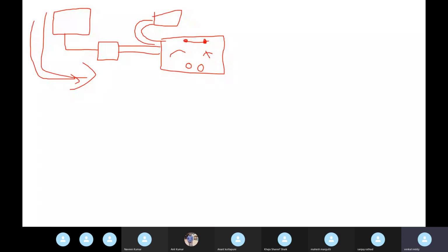Generally we don't test like 100 times or something. But how to do this 100 times? Not only one, we have so many telltale indications, so we need to check each telltale 100 times. That is the difficulty. So we will approach CAPL script. If you start the button, then it will send the signal 100 times, every 5 minutes automatically. Then it will glow. We will observe whether it is glowing or not. Got it, guys? So, customization.